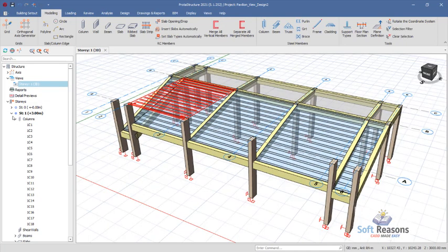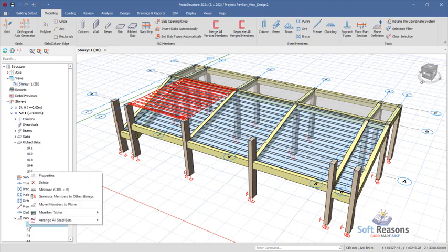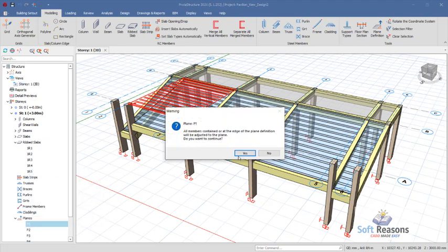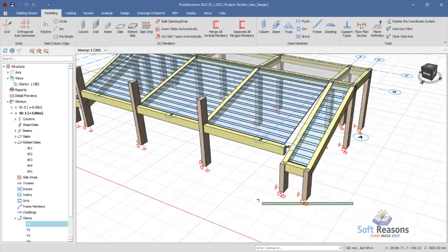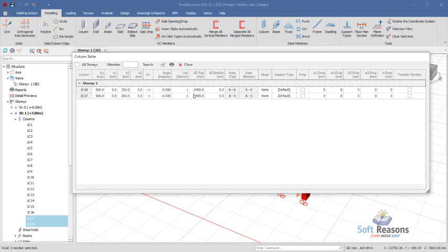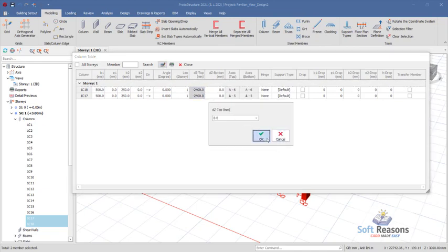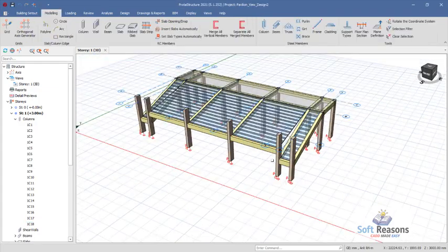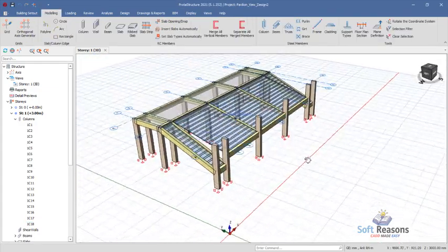Then we get to the plane provisions, expand the story 1. Get to this plane provision, which is the P1, select it right there and move member to plane, yes options, just like this. As well, remove the plane constraint. The constraint of 2400 downward has to be removed. Change it to 0 like this. Okay, so we have this. So this is what we actually intended.